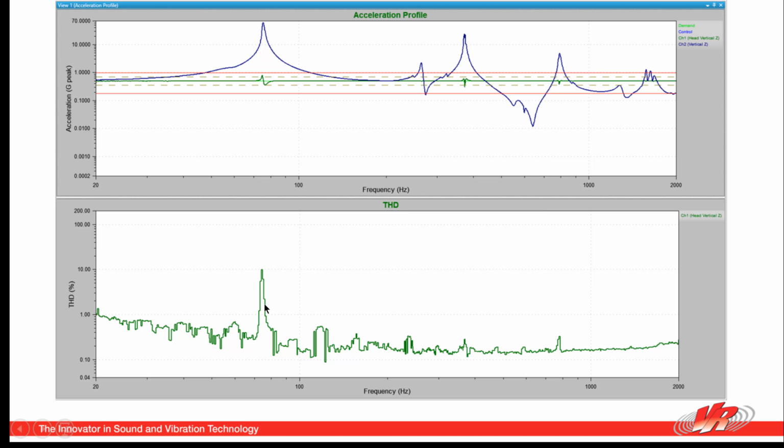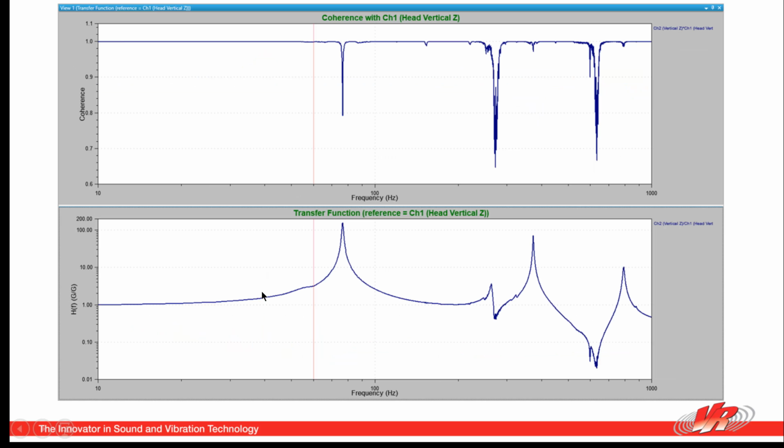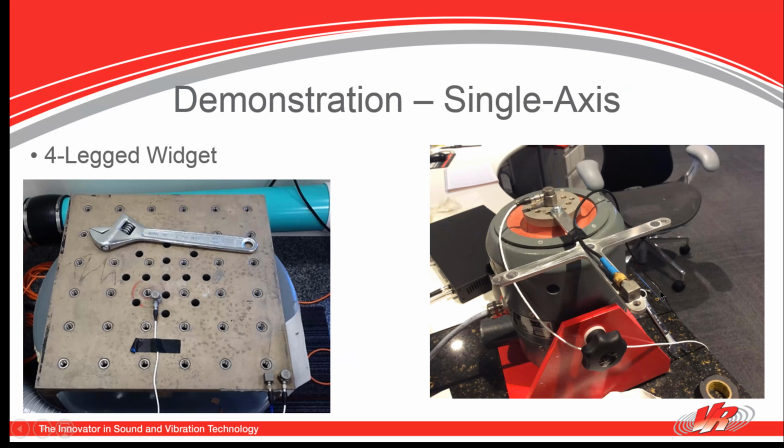There is a little hiccup here, and that's because of a resonance that we find in channel 2. There's a pretty large resonance here, and that resonance, as it vibrates, if it does, because it's attached to the head, this vibration will affect the shaker head a little bit.